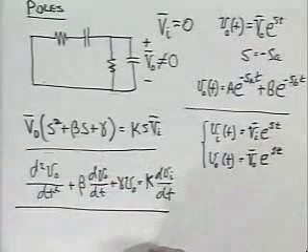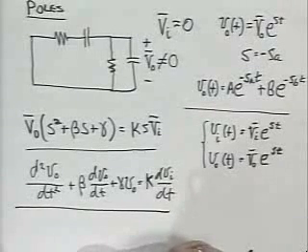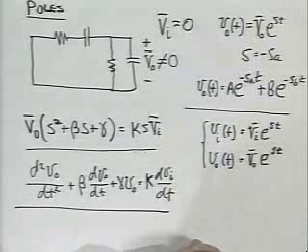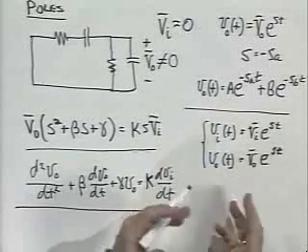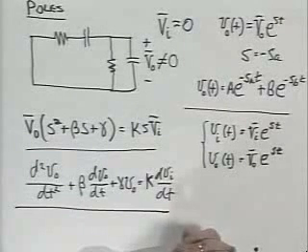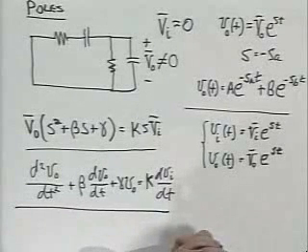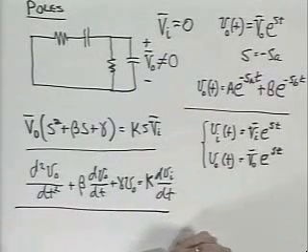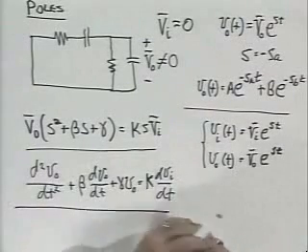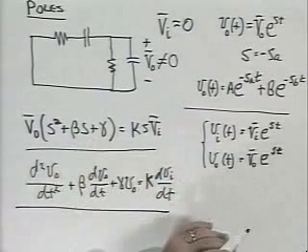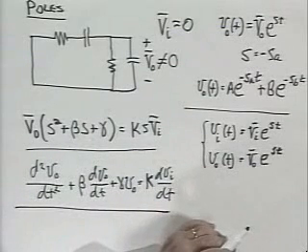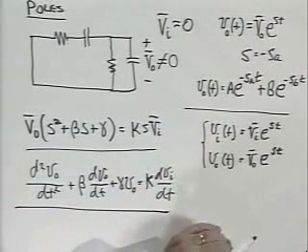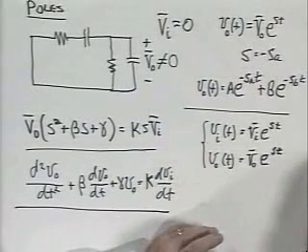So the transfer function has the additional virtue of enabling you to take a circuit of arbitrary complexity and go back and write the differential equation, which must relate two variables, a driving variable and an output variable in that circuit. And as with sinusoidal steady-state solutions, the analysis with complex amplitudes and a complex frequency S is somewhat easier. It's always easier to work with algebra than it is to work with differential equations. Before I go on and look at a second example, very briefly, let me just emphasize what we've done here.